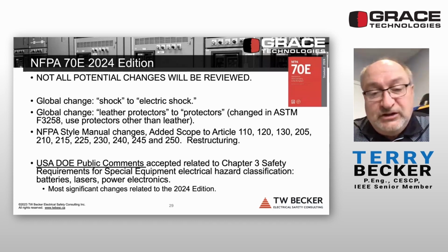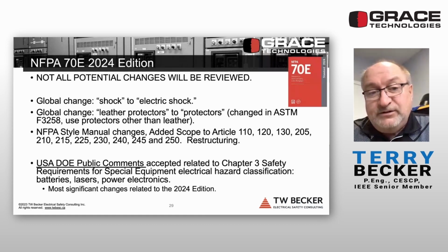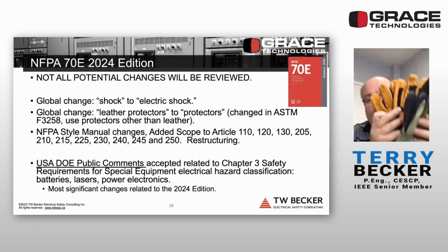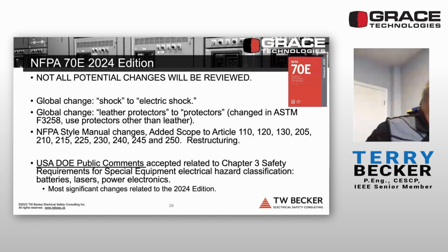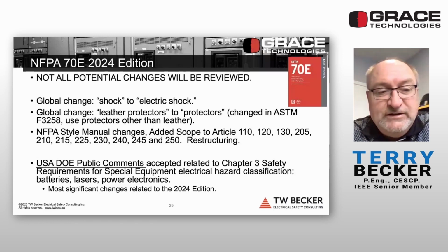The word shock has been changed to electric shock, which I sponsored. I think that's good, and that's clarity. As far as rubber insulating gloves and leather protectors, it's now going to just say protectors. There have been some changes in the protector glove that could be put over top of a rubber insulating glove. So there's some evolution in glove technology, as well as an evolution in separate arc flash rated gloves that are out there. So just manage what's changing out there and make sure that you're aware of the limitations of some of this PPE as it changes.